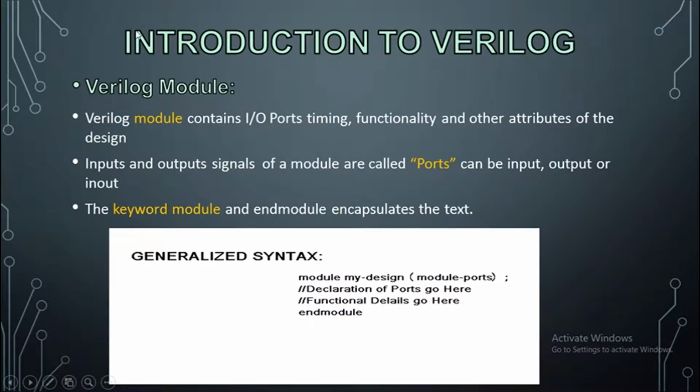Now we are going to start the third tutorial objective, which covers the very basic concepts of Verilog. In the Verilog programming language, we have a module. Every Verilog program will have a module, which is declared by the keyword module, followed by the name of the program, which I call my design, then followed by parentheses and some inputs and outputs, which are called ports.